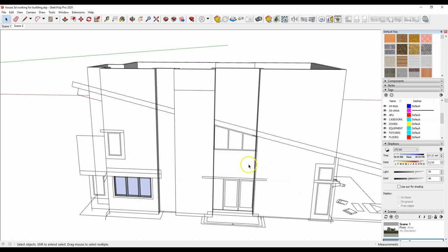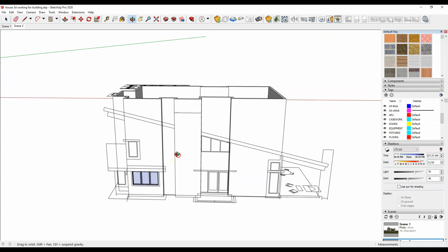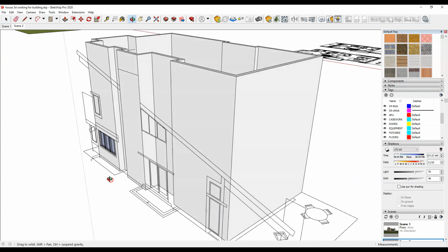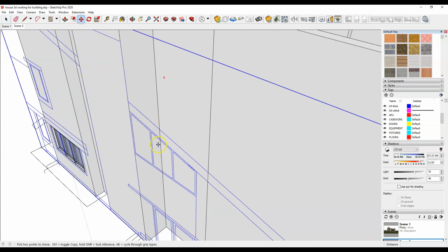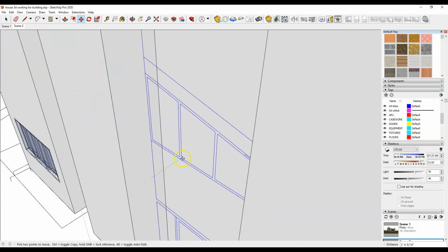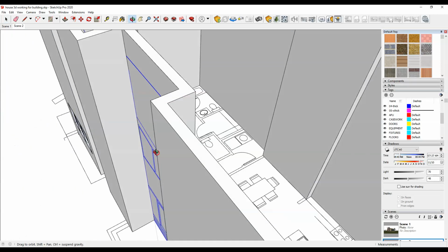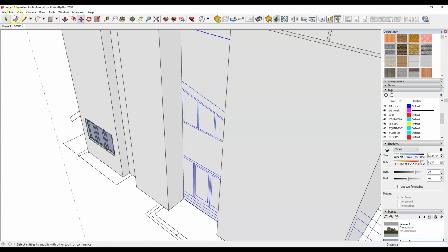And maybe I'll show one more. I might have done the steps slightly different in the videos. It doesn't matter ultimately, but the basic steps are: make the walls complete, make the holes, then make the windows. And the thing you want to notice, as I mentioned before, since these are different planes, let's say we want to put the windows here, I have to move the CAD elevation. So I can just select a surface and move this back to here. Now I can draw on this surface here.